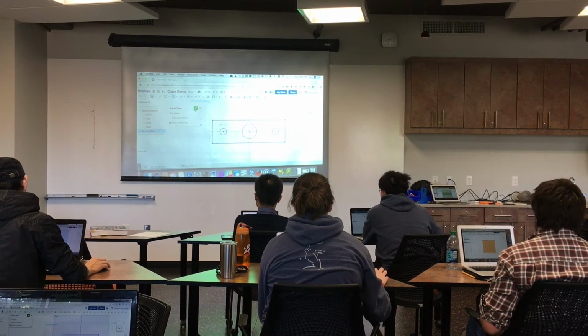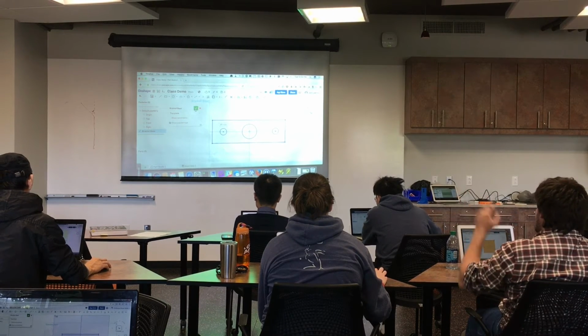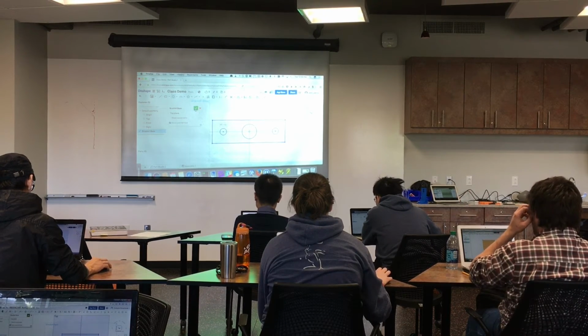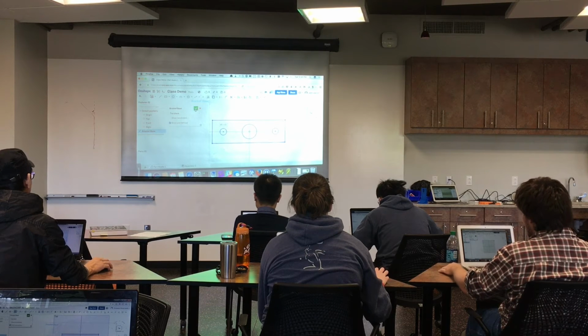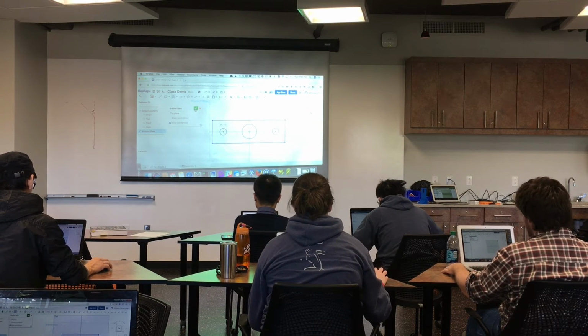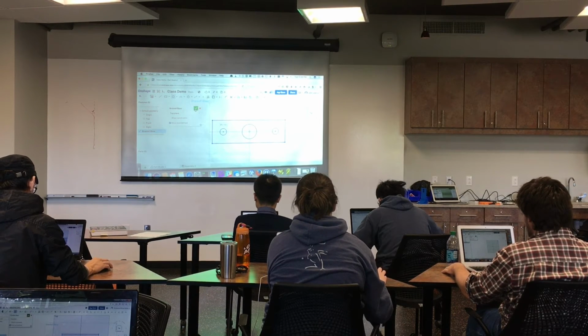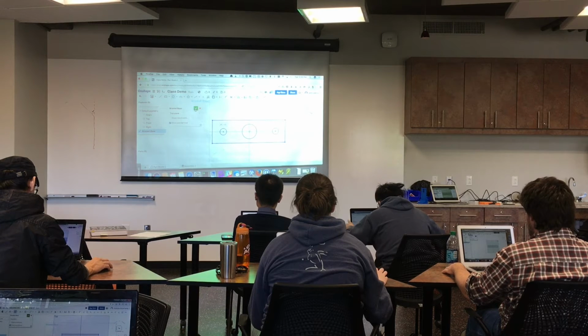So is everybody here? You missed a step. Okay, what'd you miss? Your top bar changed. Yes. Oh, so double click bracket base there. And now you're in the sketch editing it. So go ahead and hit N to get in a sane view there. Is there any way you can space those circles, or just estimating for now? Right now they're just wherever we dropped them, which we'll fix in a second.